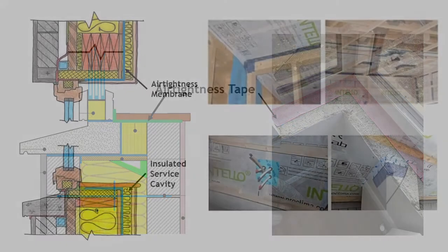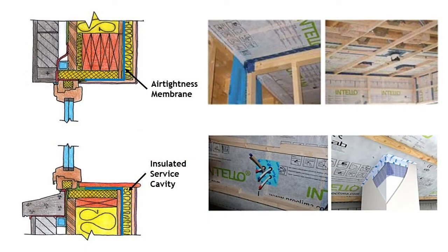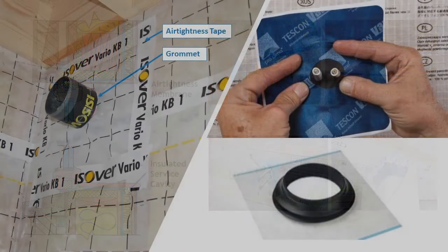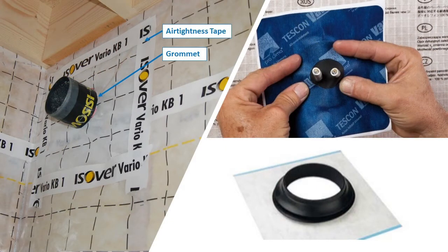Another example could be using a service cavity and an airtightness membrane. Again, airtightness tape is used at junctions or breaks in the airtightness barrier, and if there is a service, for example a pipe or wire penetrating the airtightness barrier, then a grommet would be used.